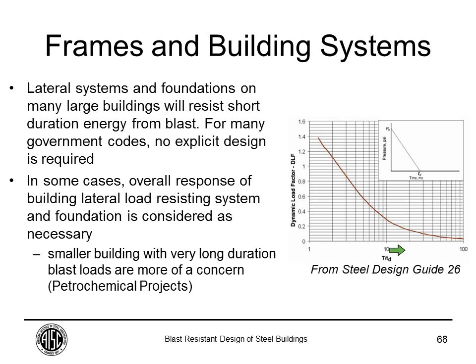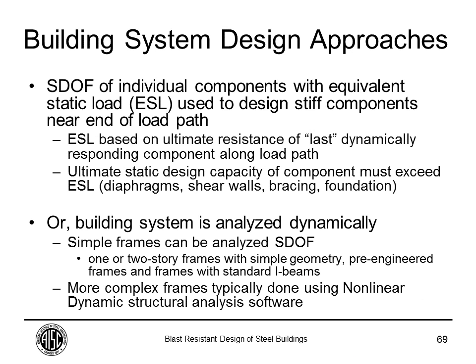So when you look at a triangular load, this plot is for a triangular load, which is what we assume for blast load, the effects approach zero. So that's the main reason that once a blast load hits a frame, the effects get dissipated and you don't need to look at the response. Maybe when you have some smaller buildings with very long duration loads, you could look at it, and that's more typical of petrochemical applications. But generally, you don't have to look at the lateral response.